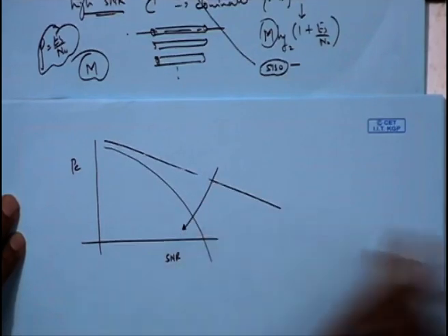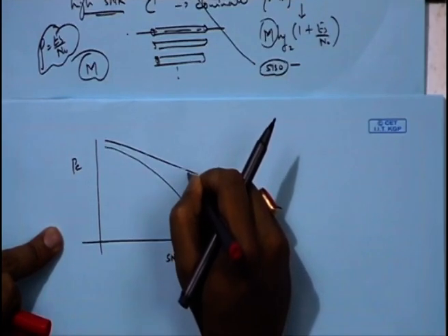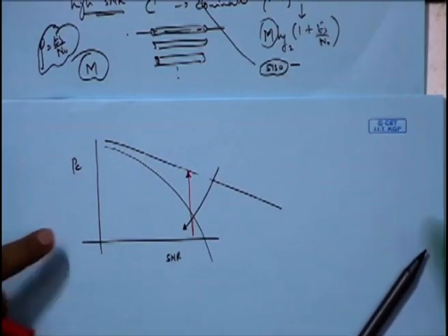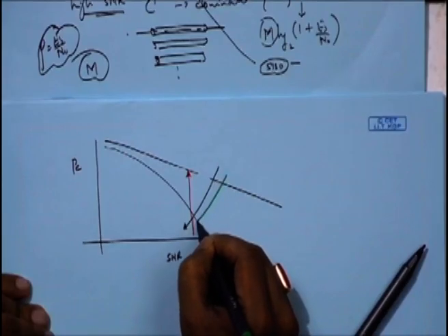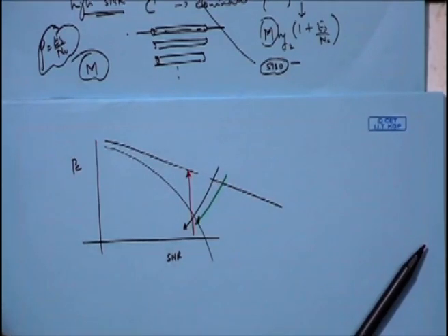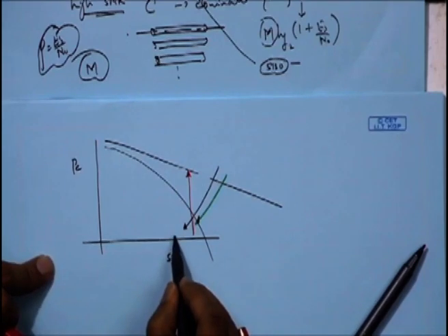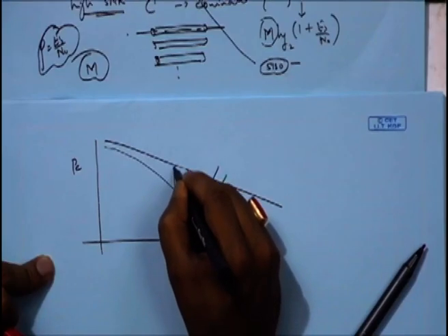So, basically there is a primary loss in error probability when you go from AWGN to fading channel, whereas as we increase the diversity order you move more towards the AWGN channel. So, this tells us that if we are already in a low SNR situation, our error probability is quite high.